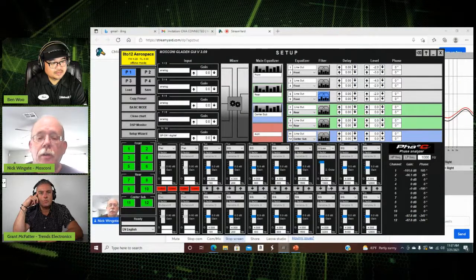For instance, this is a big one in cars, and again, 250 hertz is a pain in the ass right in here, because normally it's the width of a car. A lot of times, this is a huge problem. So if I'm running my sine sweep and I notice that 250 hertz is where I've got my null, I'm going to be handing off 250 hertz, 315, 400.